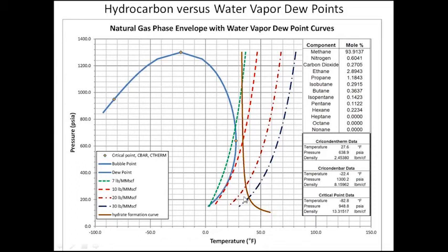Here's another look at a phase envelope, and in this case we're looking at the phase envelope for this particular composition of gas. I've included some water saturation curves on the plot, and you can see that water saturation is a completely different consideration from hydrocarbon dew point. Water dew point, and then also here's a hydrate formation curve.